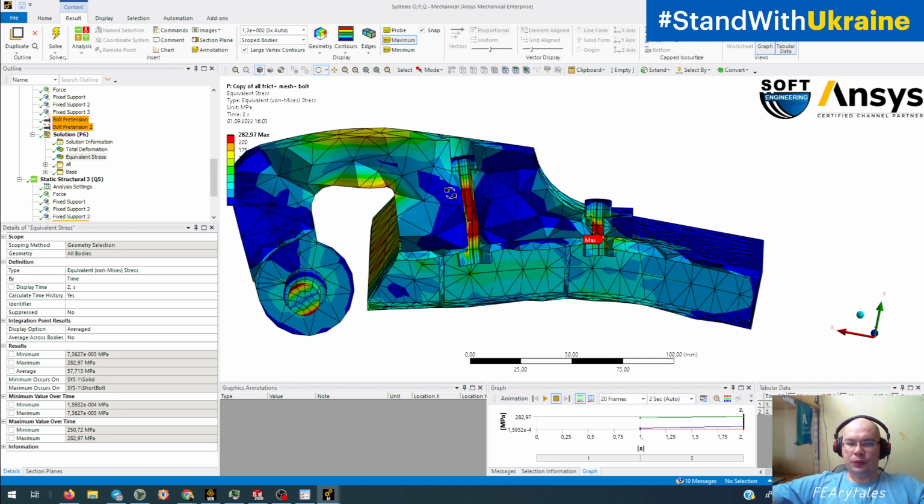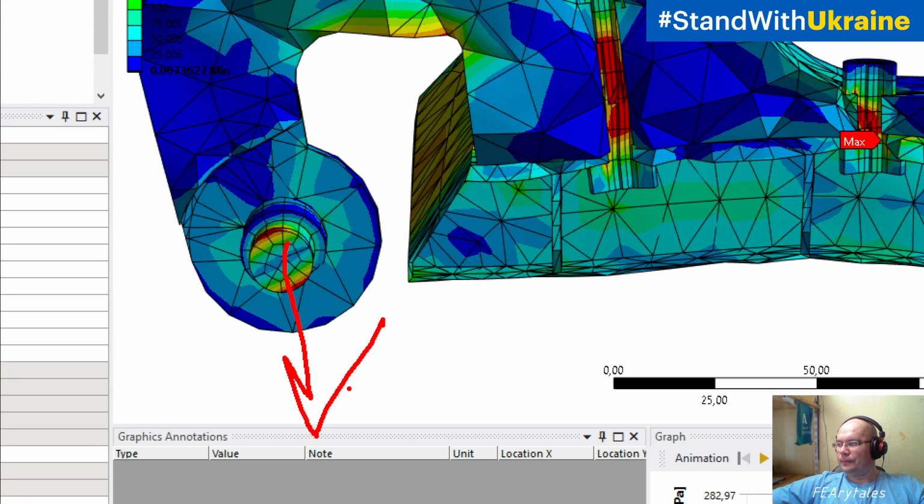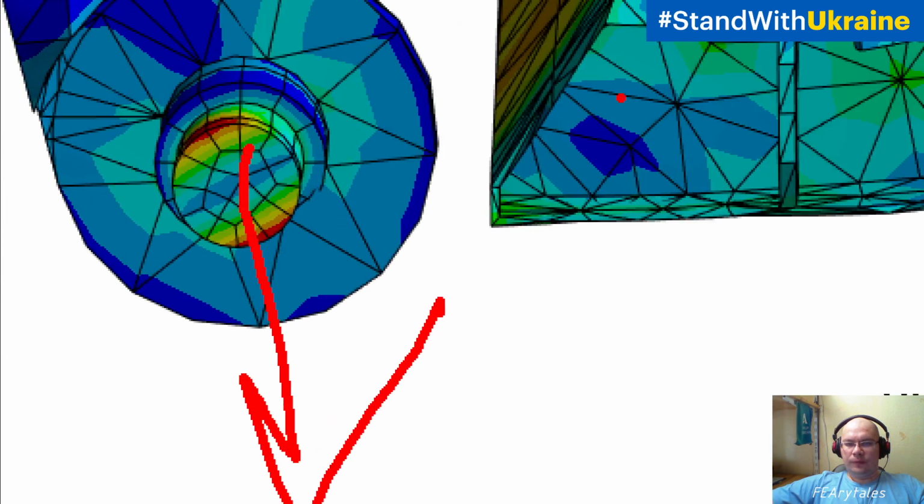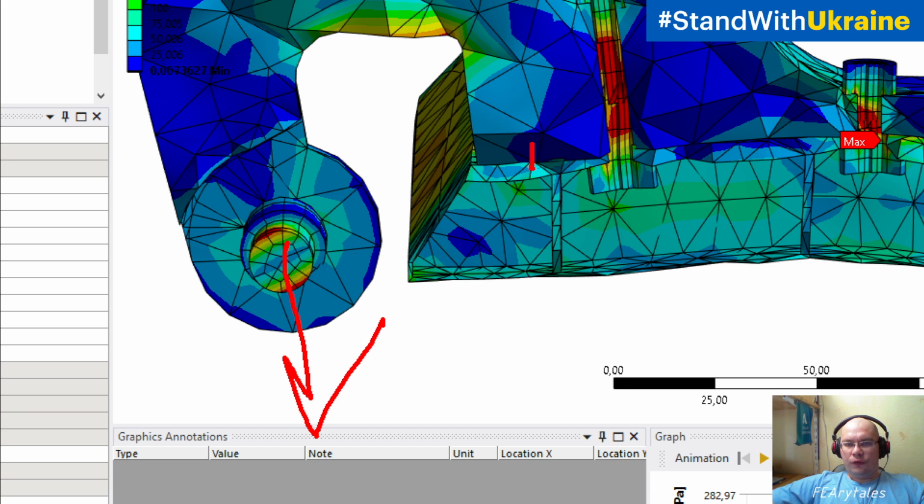And you need to understand that when we create our Bolt Pretension, we obtain force not only from this one, but additionally from this place which wants to interfere, because the bolts are preloaded and compress those two parts and try to interfere with it.